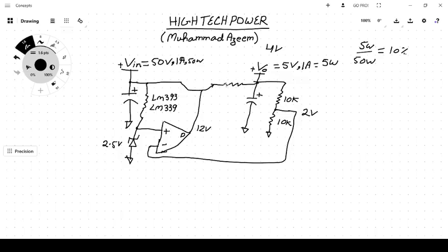So now because of insertion of the resistor, there are two effects. One is that it has reduced the inrush current that is going to the output capacitor, but at the same time there would be dissipation in the resistor as well, because it is also in series, and there would be a drop on it due to the actual value of this resistance.